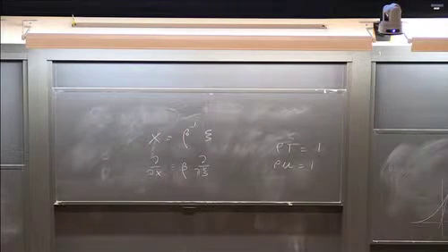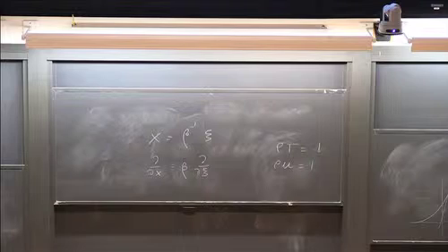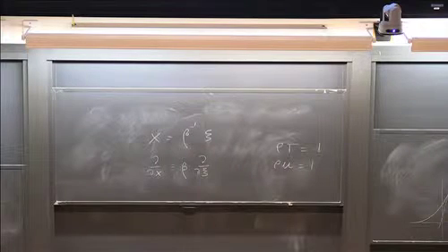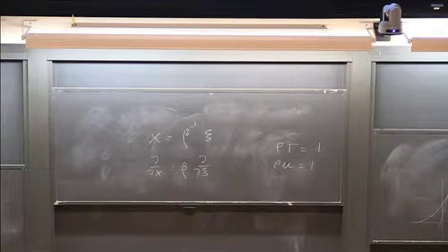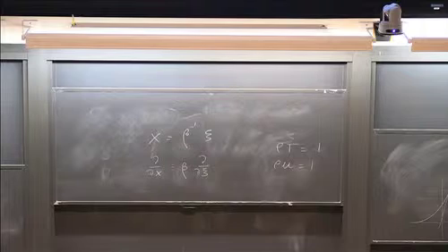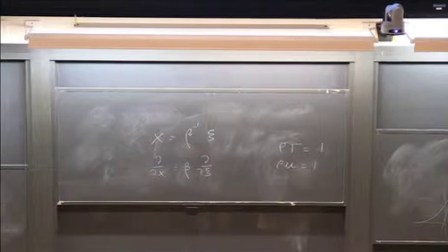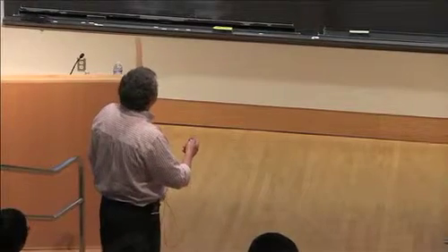Then finally, the pressure can be obtained from the momentum equation. Since we know the velocity, all we have to do is to integrate the first order equation for the pressure, and we can write an expression for it, which in fact tells you the slight drop in pressure that occurs across a deflagration wave. We have seen, remember the discussion of deflagration and detonation, that the pressure decreases across a deflagration, right? And so we can compute that.